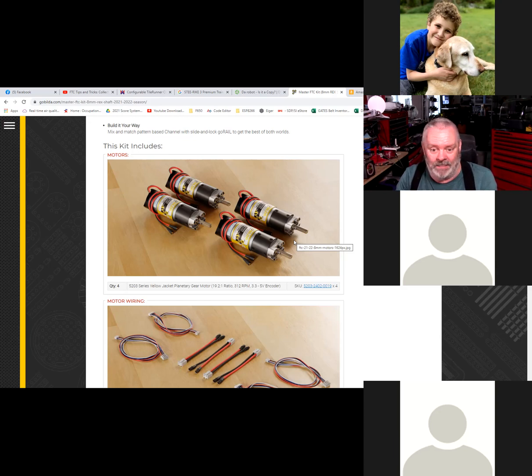And the motor classes, you can use in software. You can set up the encoders and say, drive to 3,000 clicks. And the robot will automatically move to 3,000 clicks and stop. And it'll actually hold its position there unless you tell it to do something else. So it's a nice way to navigate if you need to. So, this is a great choice of motors.